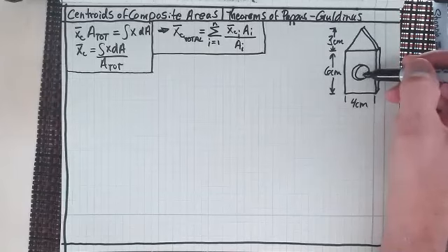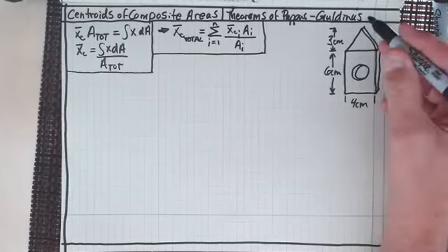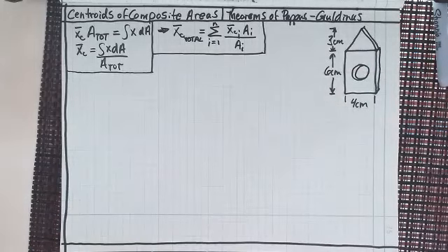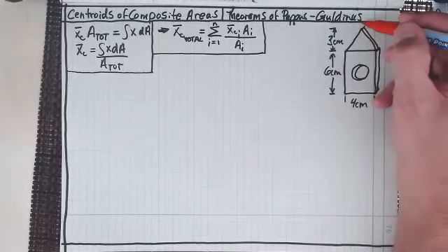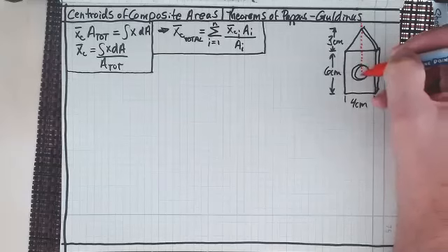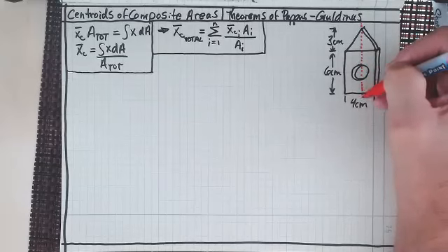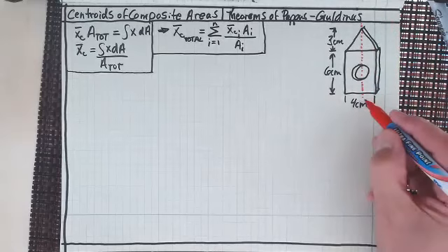So when we're trying to figure out what the X and Y centroids are of this, I think everybody can see what the X centroid is. Let me just draw that there because it's symmetric. And this is something that I wanted to bring up too. If we have something that's symmetric about a certain axis, then we know that the centroid has to fall along that axis.